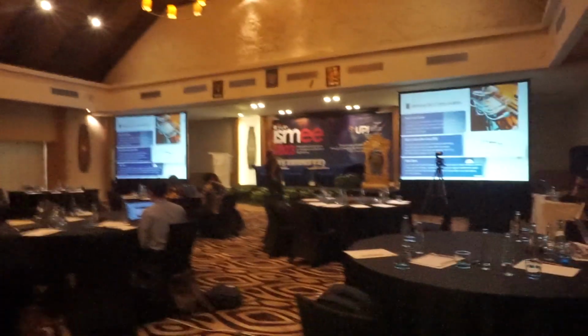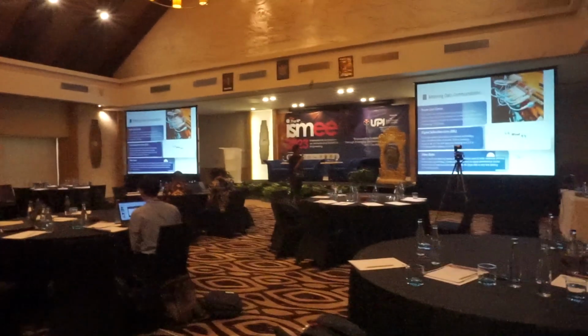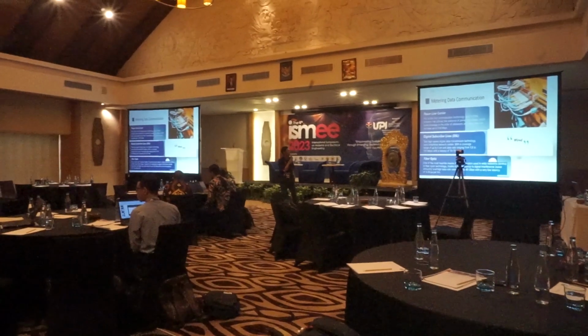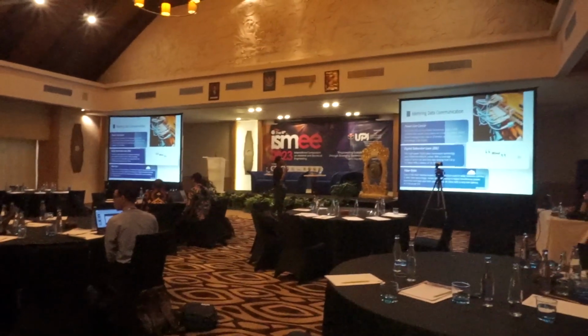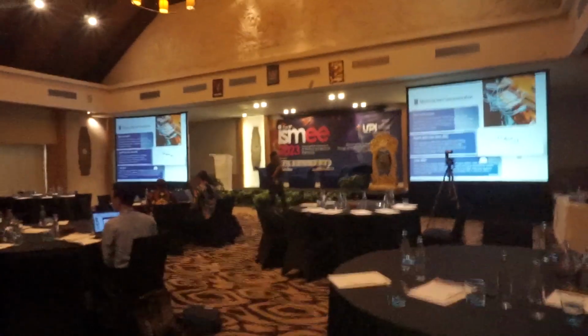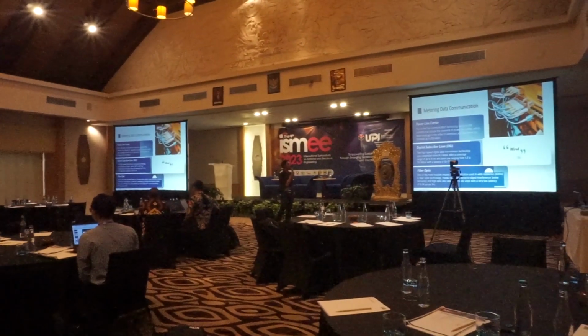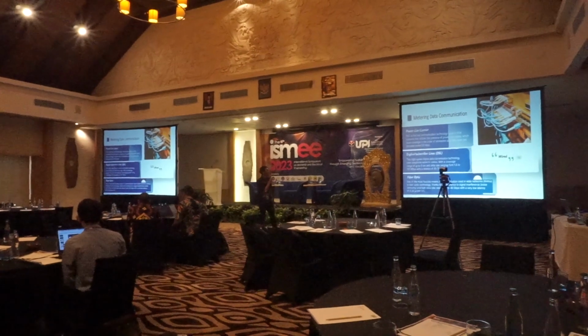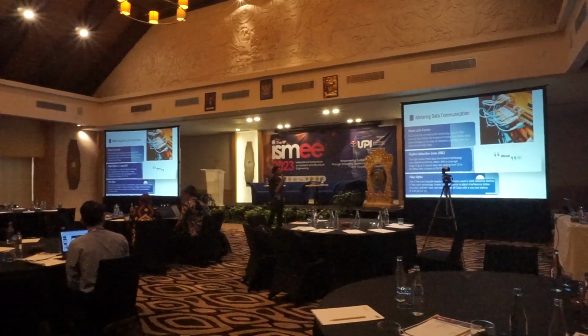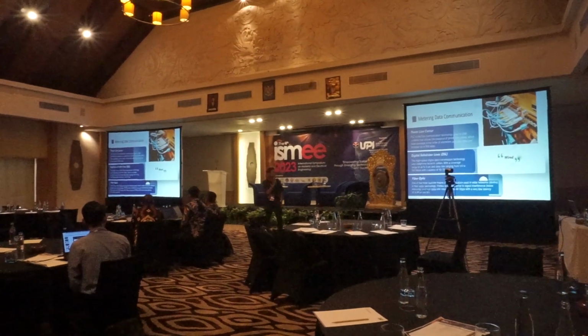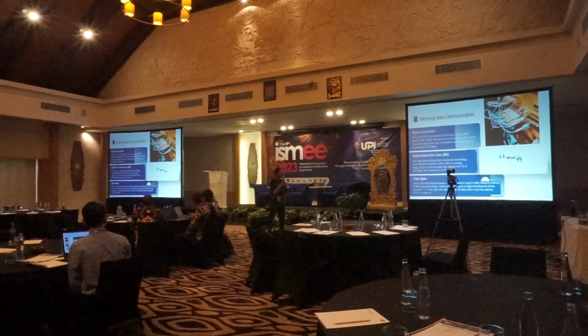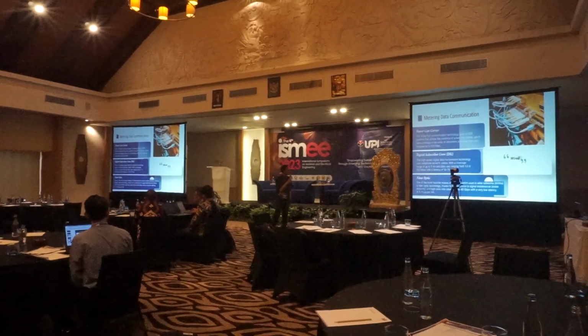The first one is power line carrier or PLC. PLC is the first communication technology used in smart meter systems that utilizes the presence of power line cables, which have coverage in the order of kilometers, and data rates can increase up to 500 kilobits per second.